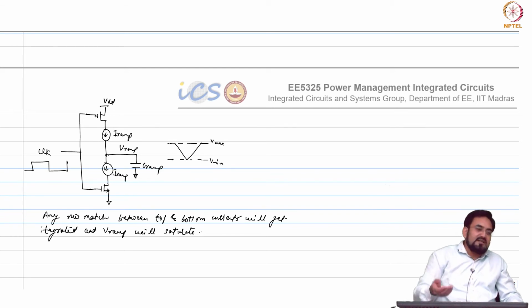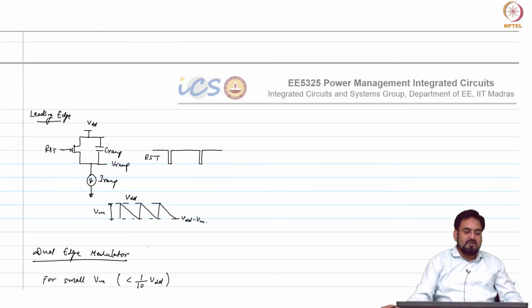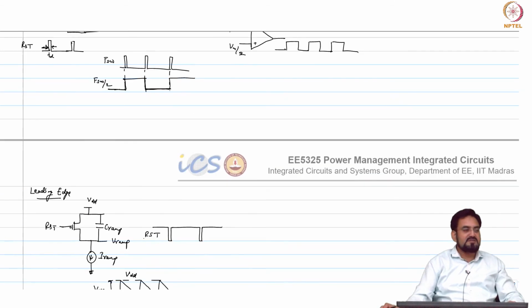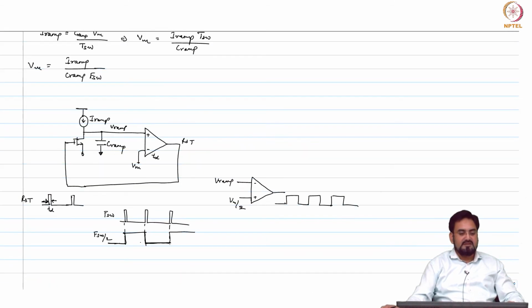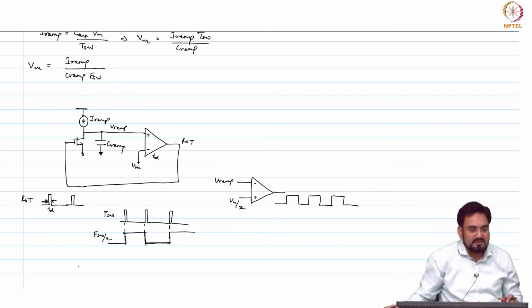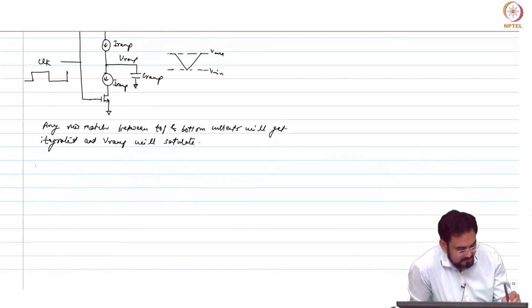Go back to your oscillator. Huh? What was the oscillator doing? What was limiting in the oscillator? What are we limiting here in the output ramp? Voltage, huh? So you can limit high and low voltage. That's it. It will never saturate. You need two comparators here.